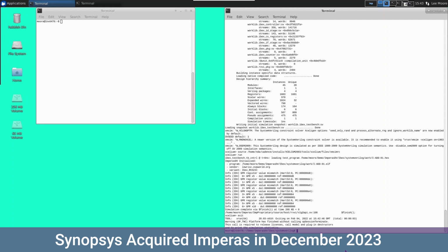And what it tells us here is that this program counter where we've executed an instruction, which is D8, we've got a miscompare. It's telling us that the device under test told us that the value of the X5 register was 0, and the value of the X5 register in our reference model under ImperasDV was D8. Because we've got the miscompare throttle set to 5, the program does actually continue executing, but of course this is continually reported. And then we see a further miscompare at this point, where we also have a miscompare